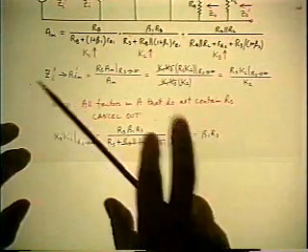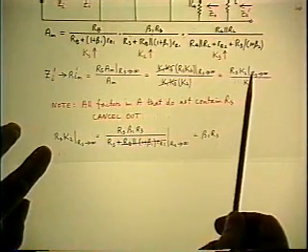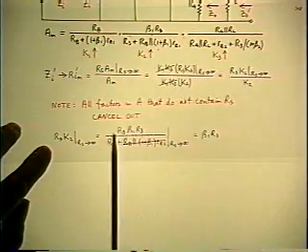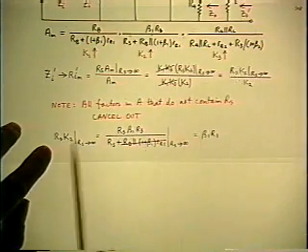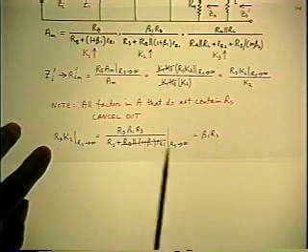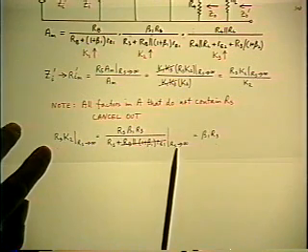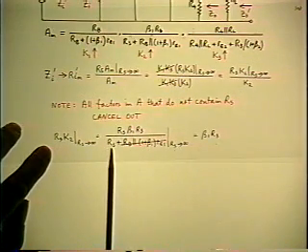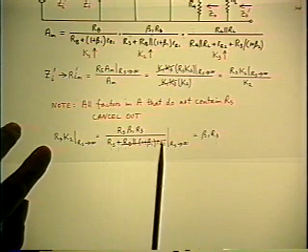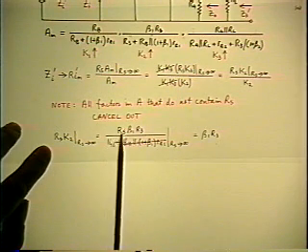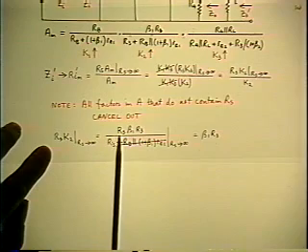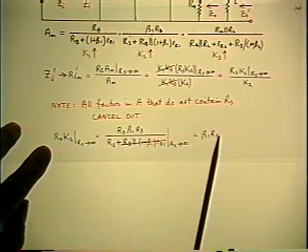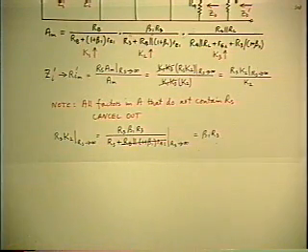So, determining the limit, K2 is the middle fraction, multiplied by RS, and let RS go to infinity. So the denominator goes to infinity, and you drop the rest of it. That allows RS in the denominator to cancel the 1 in the numerator, and you're left with beta 1 R3.